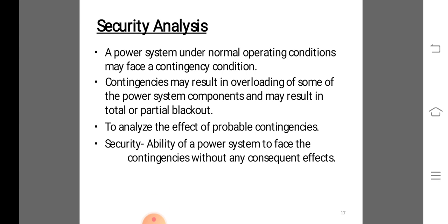Power systems are designed to survive all probable contingencies. A contingency is defined as an event that causes one or more important components, such as transmission lines, generators and transformers, to be unexpectedly removed from service. Survival means the system stabilizes and continues to operate at acceptable voltage and frequency levels without loss of load.